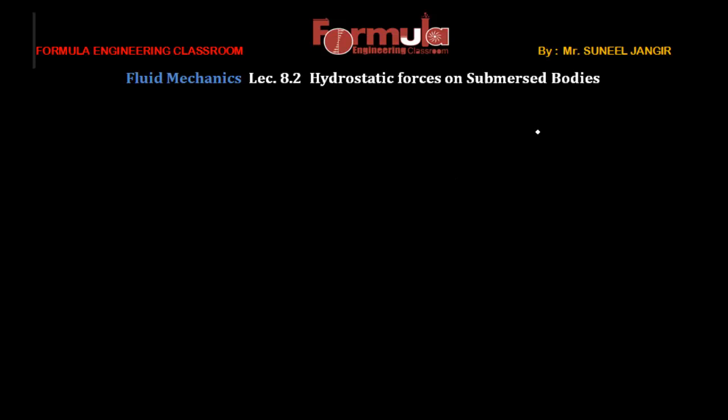In the last case we discussed that the force exerted by a fluid on a submerged body can be calculated by the formula F = WAYC. Here W is the specific weight of fluid, A is the area of the submerged surface, and YC is the distance of the center of gravity of the body from the free surface of fluid.